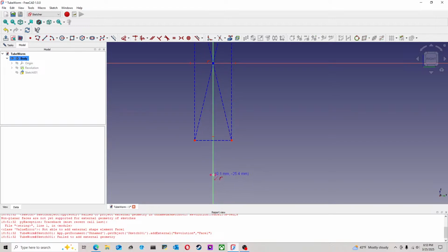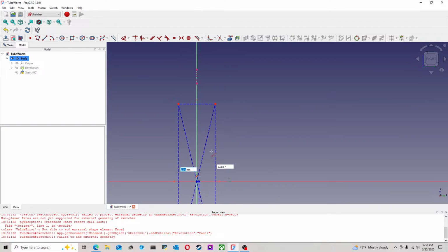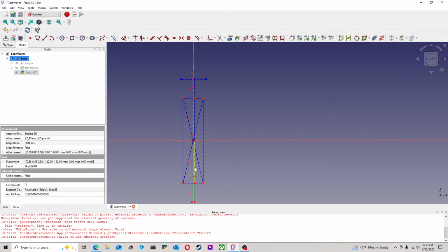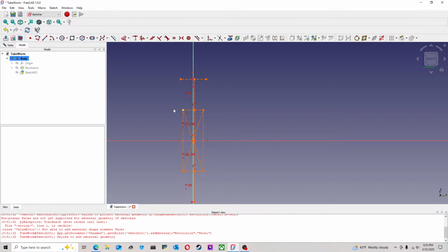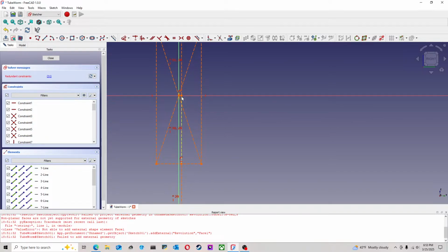And then what I'm going to do is come up here and then draw another line up to here. I'm going to draw 4 lines up to there. I'm going to draw another line up here and another line up there. Set this to coincide. And then I'm going to set these 4 lengths to be equal to each other. And it's going to over-constrain the geometry. Why did it do that? I don't know why it did that necessarily.